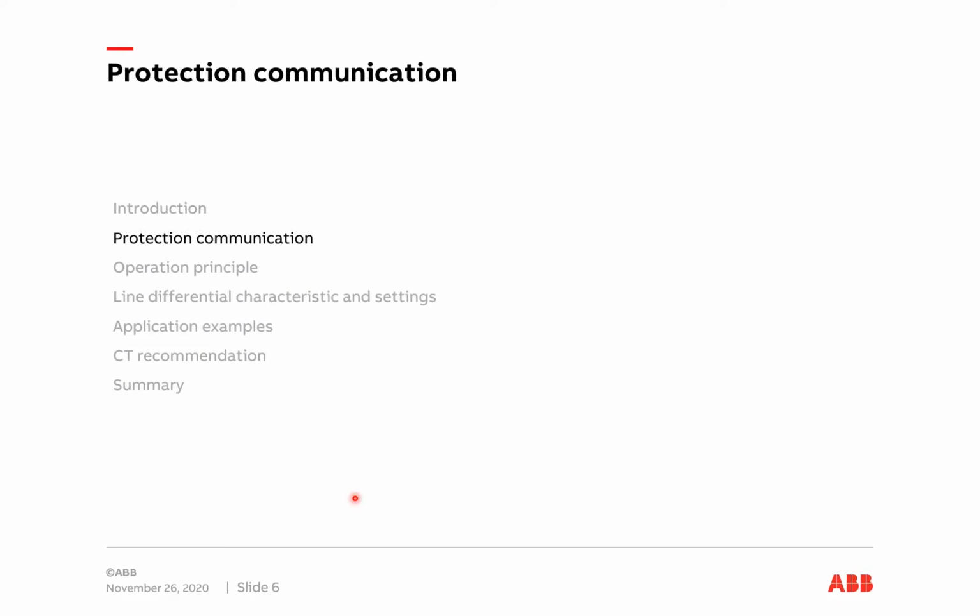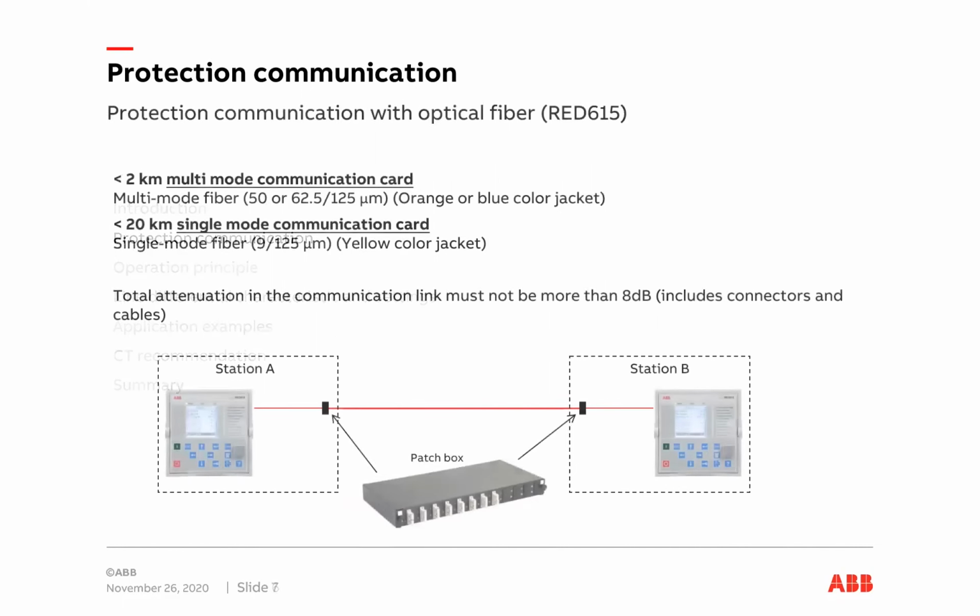Okay, so let's then have a look at the protection communication. As mentioned, it's either an optical fiber or a galvanic connection. If it's a fiber, we support two different types: multi-mode fiber or single-mode fiber.